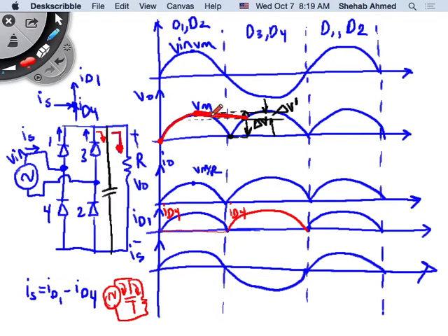My supply voltage, which is the blue, starts to go down. It's starting to go down after it reaches its maximum value. I have chosen a capacitor value to be large enough so that when I draw current, when my load is connected, actually let's do the case without the load connected. If the load is not connected, so there's no resistor here, what will happen? The capacitor will charge, the source will charge my capacitor.